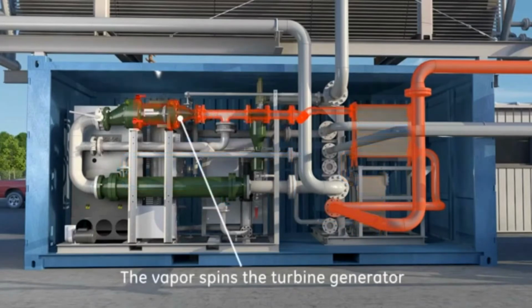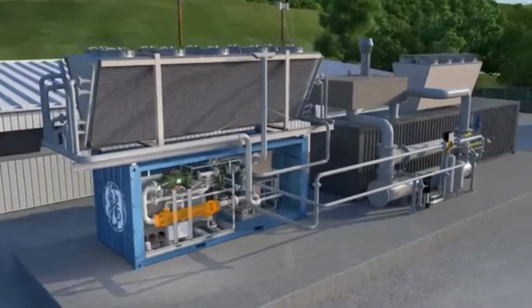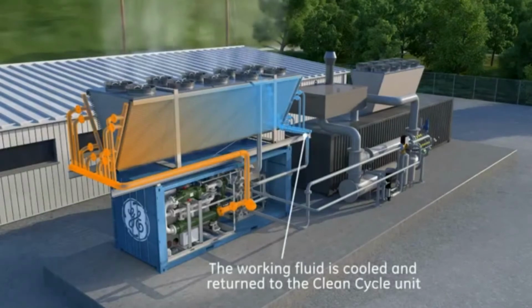The working fluid is cooled and returned to the clean cycle. The third component from the organic Rankine cycle is condenser. The remaining steam from the turbine is condensed into a liquid with the help of cooling water from cooling tower with an isentropic process, so that the steam turns into a liquid with the temperature and pressure also decreasing in the condenser. After it becomes a liquid, it is pumped back and raises the pressure to a height again, then flows into the evaporator or boiler again, and occurs repeatedly or cycle.